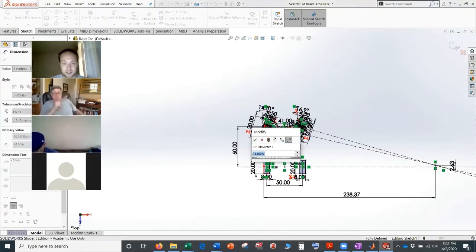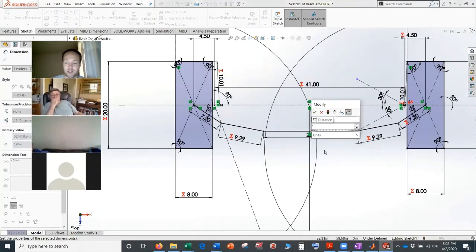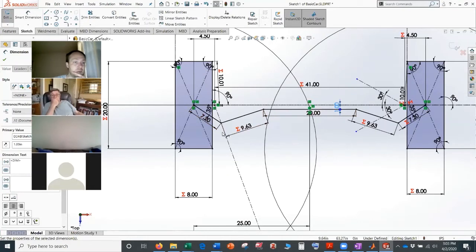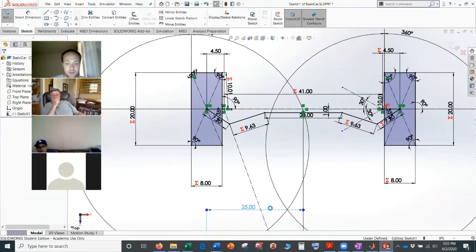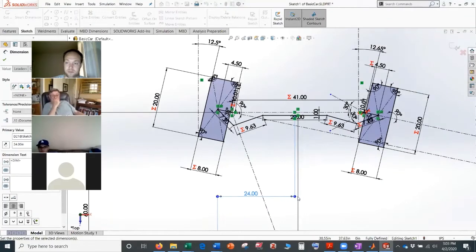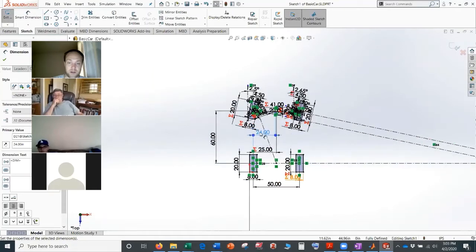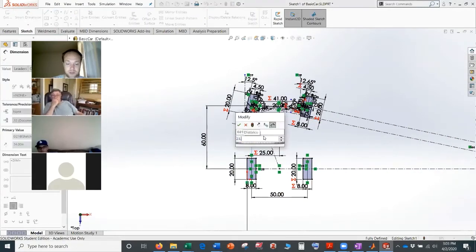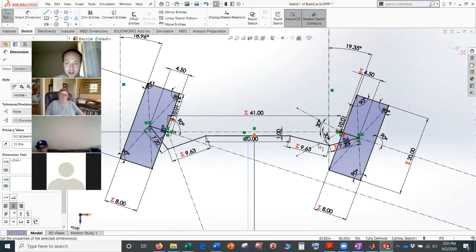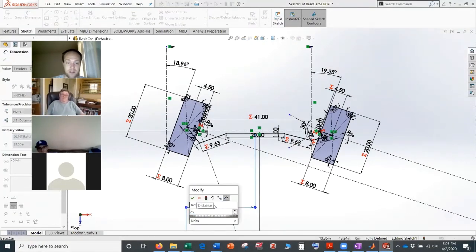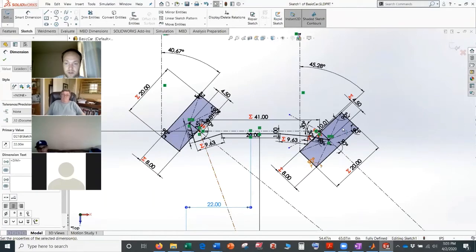Let's see here, and we'll see how in this case, because we have a rack, we move this to like 1 inch. So we'll move our rack closer up to the center line of our car, basically, right? So now our rack's up here. We still have the same Ackermann. Let's go to 24. Not even meeting yet. So here we can go a little further now. See, are we going over center yet? Nope, not yet. So now we got 2 inches of travel on our rack. 23, 22. So now it's about to kind of go over center.